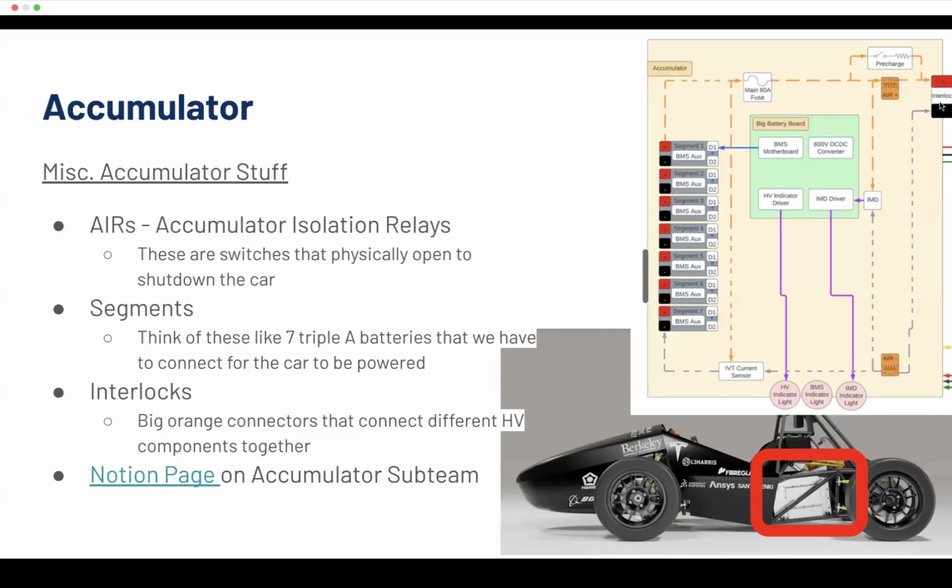You actually have to look for them. They're not as obvious. Those 2 are actually shorted to each other inside of a housing. And the reason for that is when this interlock goes on and then latches down, that little short is part of the shutdown circuit. So this interlock has to be installed correctly for that piece of the shutdown circuit to be completed.